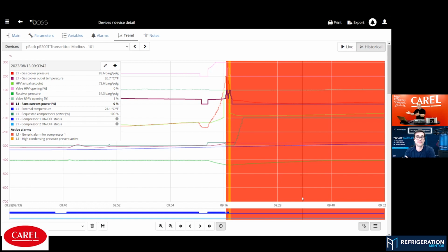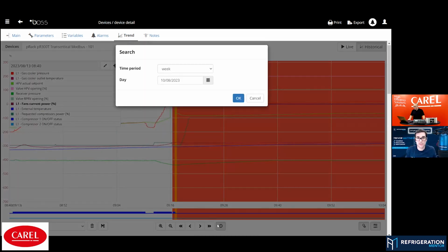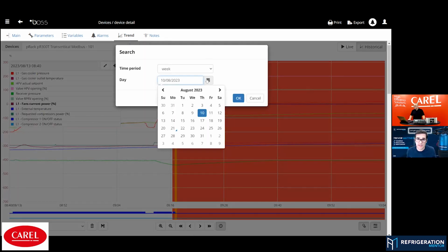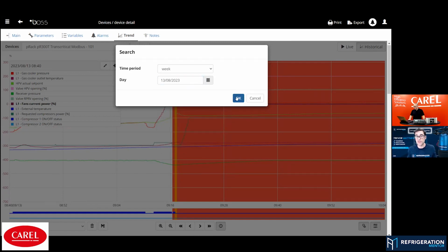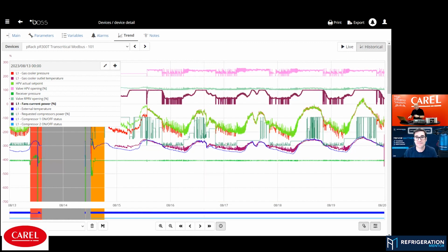So now we have found a problem. There's a blocking valve. Okay, so far so good, so easy. You said for anything from the compressor to the high pressure valve, anything in that line could be causing that issue. So now we have to figure out what's in that line. Exactly. And we figured out directly here, it only can be this high pressure valve.